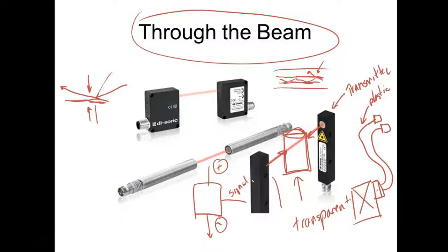So normally most of your sensors now can either be hardwired, which means the wires come right out of it. The advantage of those is they're cheaper. Or you can buy them with connectors. The advantage of connectors is that if it goes bad and you need to change it, you can just take that little connector off and change the sensor out without rerunning wire.